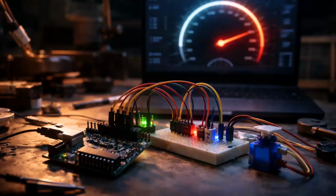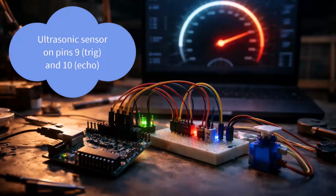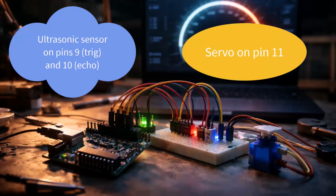The hardware is exactly the same as lesson number 2. We have an ultrasonic sensor. The trig pin connects to pin number 9 on our Arduino board, and the echo pin to pin number 10. The servo is connected to pin number 11, and we just have the same power connections.